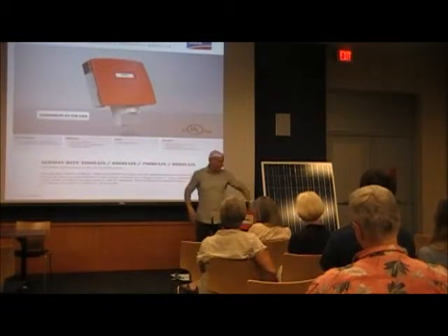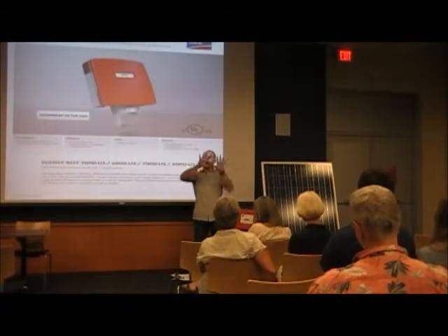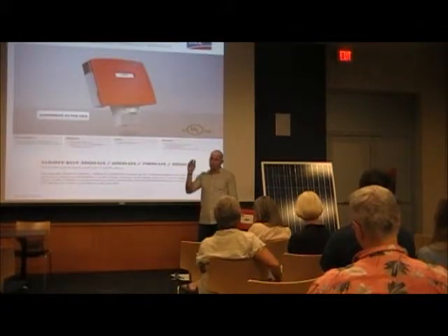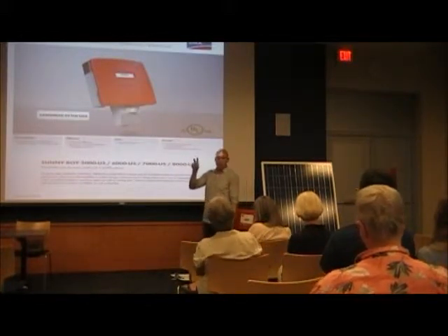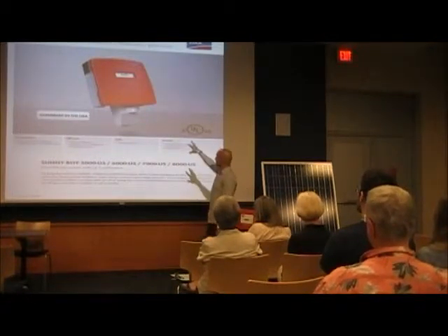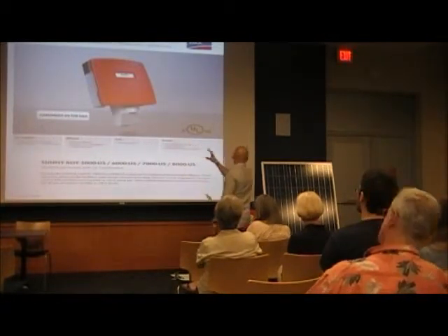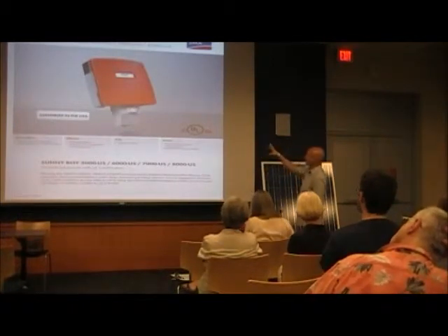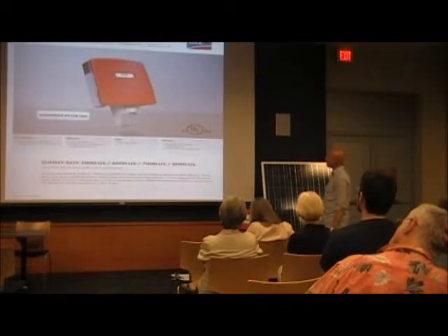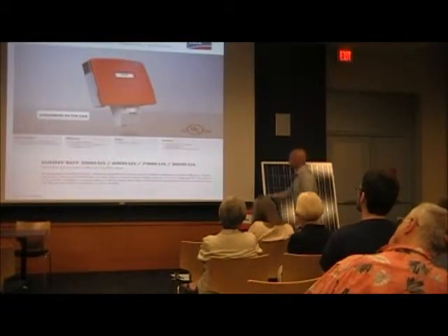So now you can actually set modules flat instead of having them track, and these inverters will always track the perfect voltage amount, so you get the most benefit off your module. A lot of advancement has happened in this, and they've gotten smaller and more efficient. This is about 96% efficiency, maybe 97 on the peak.